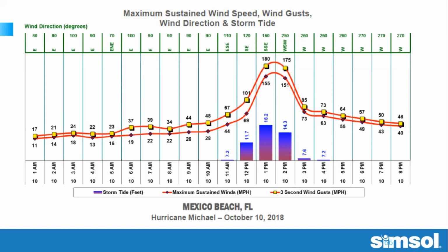Well, if the first floor is submerged, is it going to be affected by wind? No, it can't. It's underwater. So by the time the surge gets above the second floor at 16 feet, the wind's at 155 miles an hour. At that point, your second floor framing's gone, your roof slopes are gone, most of the shingles, the roof slopes themselves, let alone the shingles, are gone.